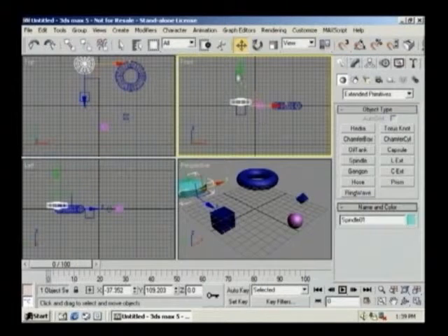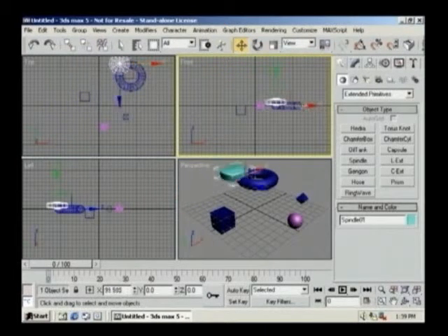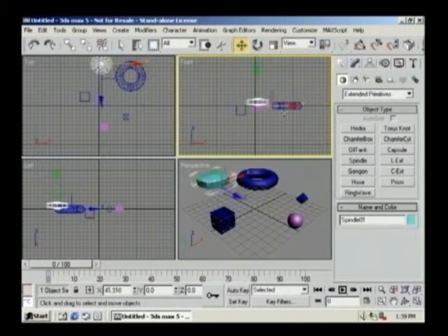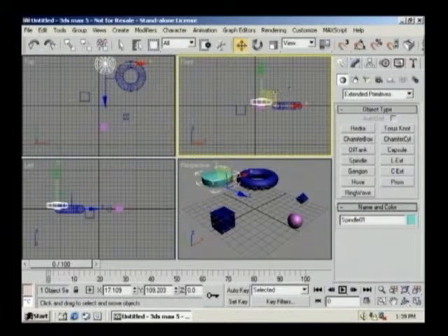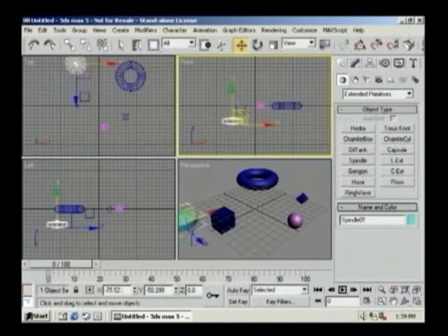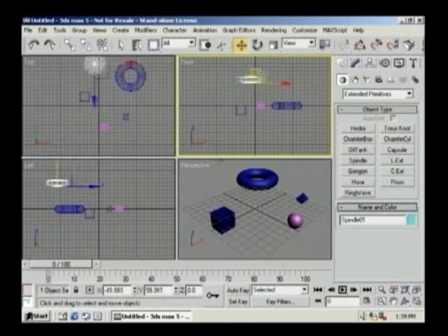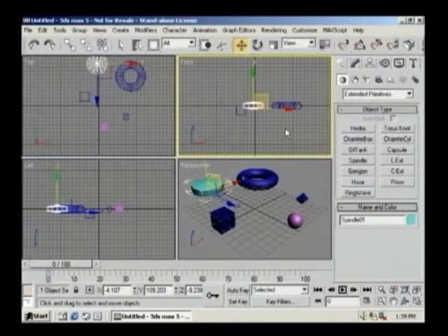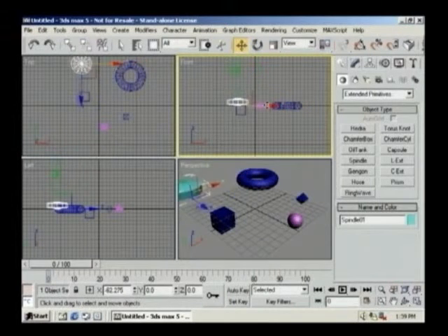First thing you're going to notice is that you have handles that represent each of the three axes. And you use the Select and Move tool to move objects, obviously. But if I click on just one of these axes arrows, I am now constraining my object's movement to that axis. You can also move an object in multiple axes in a viewport by clicking and dragging on this plane or the different planes you'll see in a perspective viewport. Just by clicking on this area and then dragging around, I can move on two axes at once instead of just one. We'll discuss all the transformation tools in great depth later, but right now I just want to introduce you to some of the tools before we move on.